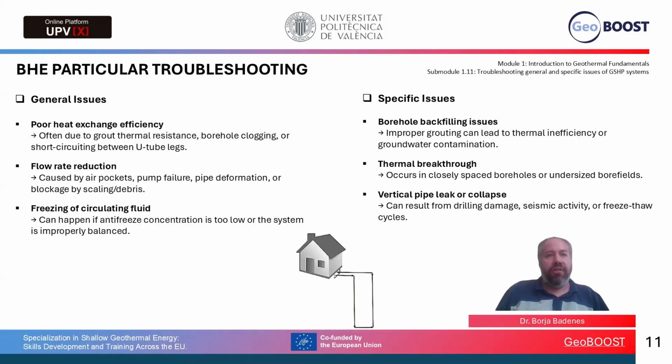For vertical borehole heat exchangers, the issues that we have to face are the following. General issues: a low heat exchanger efficiency from the ground resistance, clogging or U-tube short circuits, flow reduction from air pockets or scale, fluid freezing from the low antifreeze concentration. About the specific issues, we can find poor grout backfilling, thermal breakthrough between nearby boreholes, and pipe leaks occurring from the drilling damage or freezing cycles.